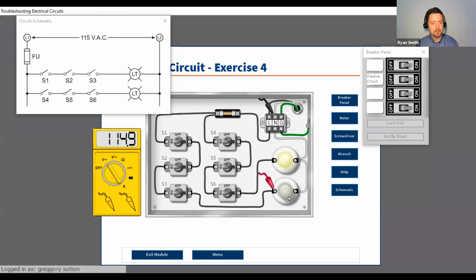I think the light's probably not good. The bulb's probably blown out or something on this light, is my guess. And you might be right. However, does that light bulb need just a hot, or does it need a hot and a neutral? That's a good question. It needs a neutral too. Yeah, every hot needs a neutral. So we verified that there's a hot there, but we haven't really verified that there's a neutral. Now, if we verify there's a neutral there too, and you get 120 volts to that light, then you were right. It's a bad light bulb.